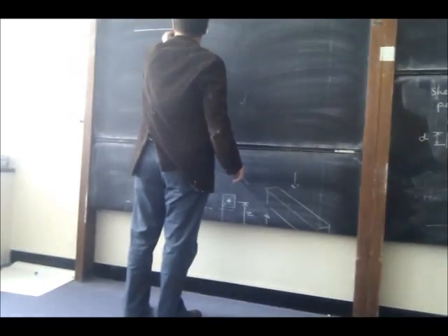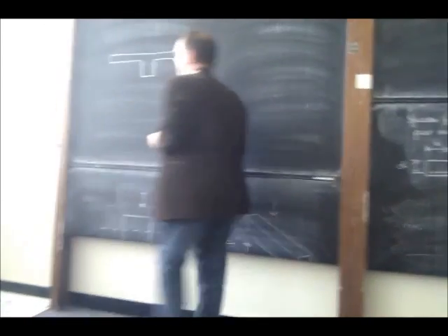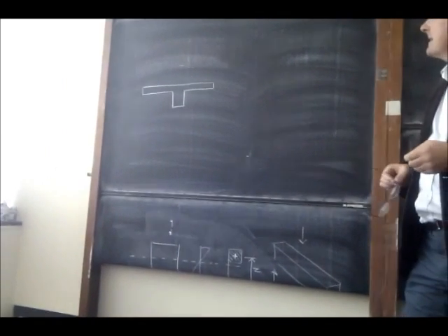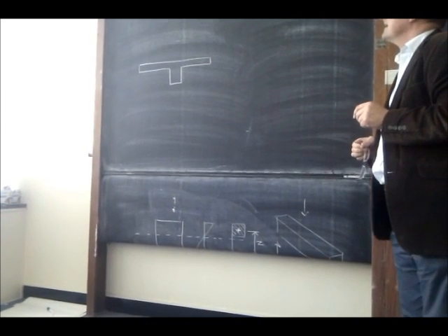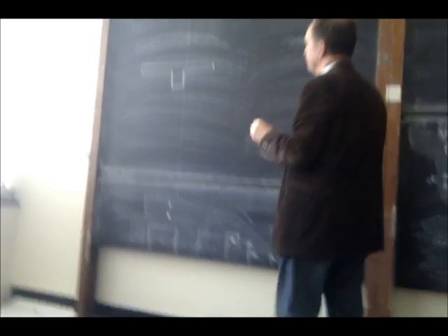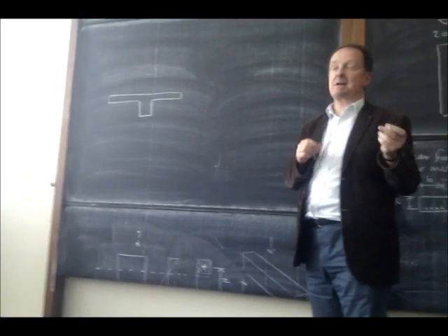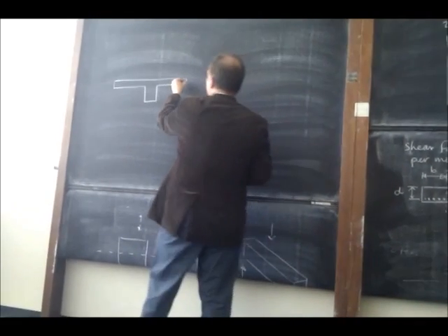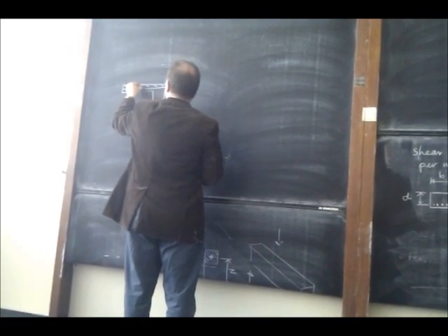Just go through the whole class. So you've got a beam like that, and the top flange is in compression, and the reinforcement in tension is in the bottom. There are a number of possible scenarios in terms of the way it's going to work. First of all, it depends on where the neutral axis lies. If the neutral axis lies within the flange, then obviously the width of the concrete in compression is going to lie wholly within the flange.